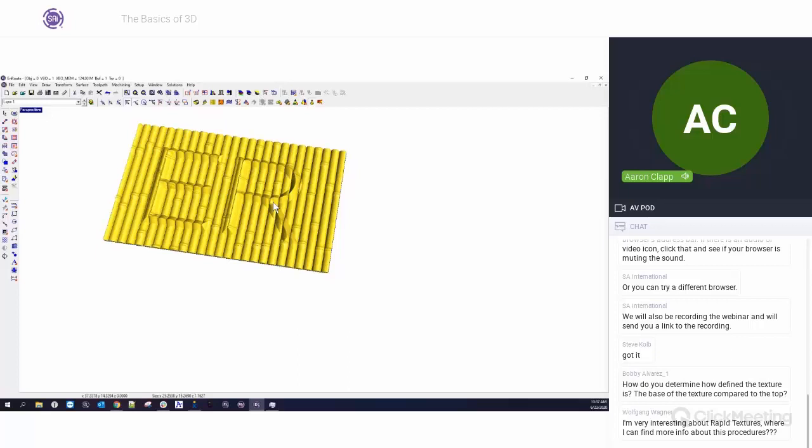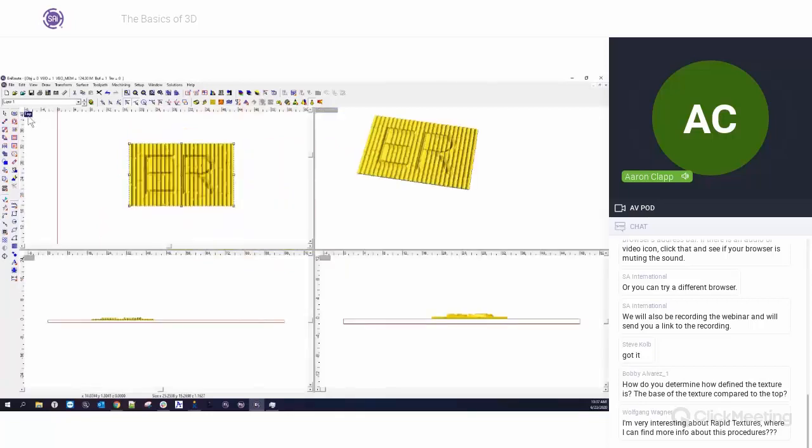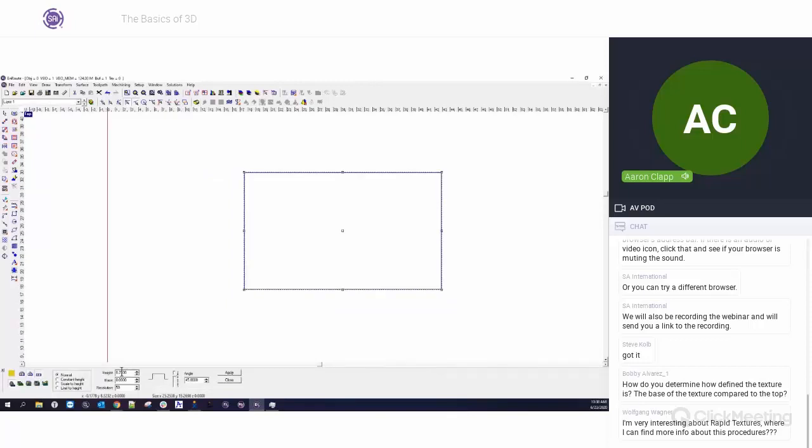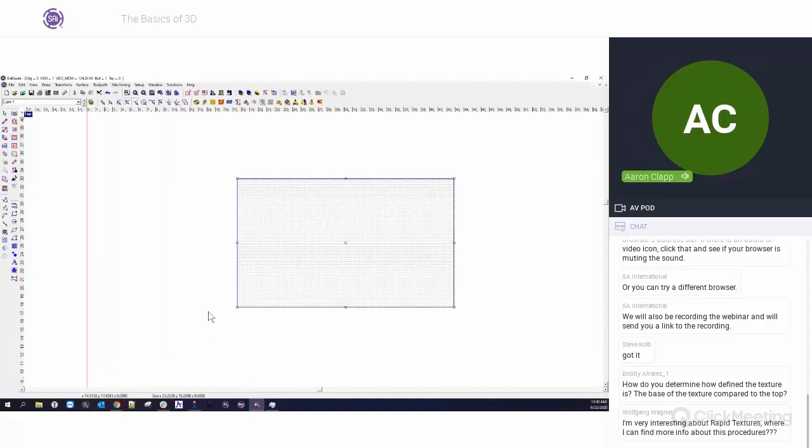So the big key things that we want to remember from this whole episode is, when you're creating a relief, you always need to start out with a base relief. It doesn't matter what you're doing, you always need to start out with the base relief. And we do that by clicking on Create Relief, Add, Flat, and Zeros. That gives us a base canvas to work on.